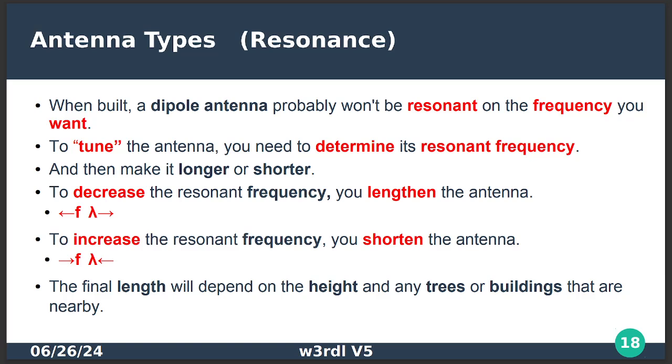So if you want to cut off an inch, only cut a half inch off on each end, because that makes your antenna physically a full inch shorter. And if your frequency needs to go down, that means your wavelength needs to go up, and it's harder to add it on to the end. If you've just folded it over on itself, then you can pull some more out, but it's much easier to just snip a piece off on the end.